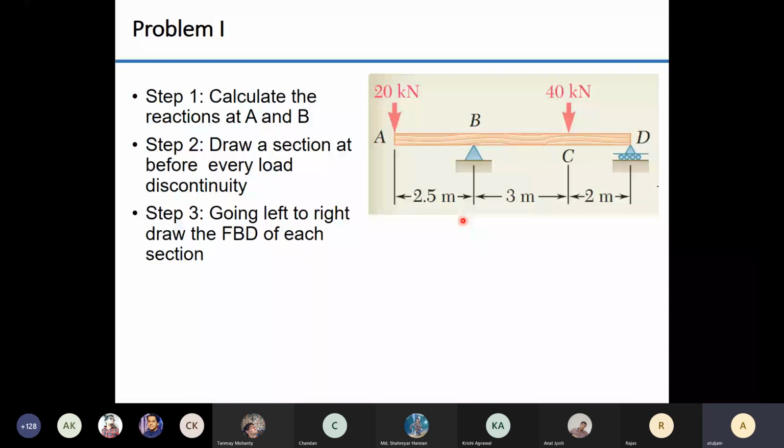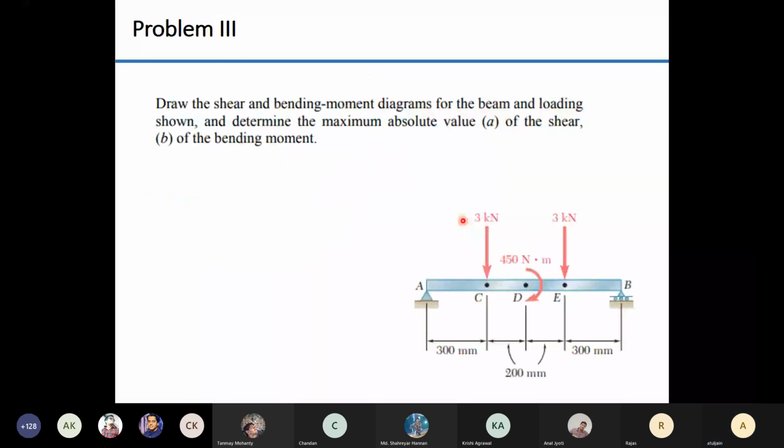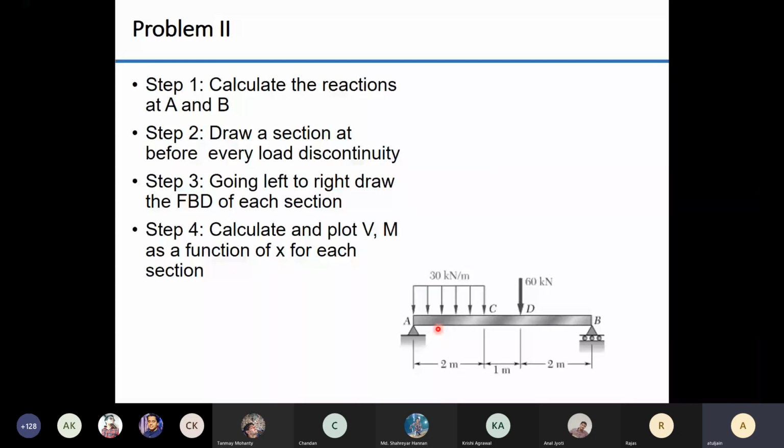Like for example, this is a good example. So let us look at this problem, okay? Now in this problem, I have a beam which is subjected to a point load, which is also subjected to a uniformly distributed load at some point. Now, you know how to draw the bending moment diagram if only the uniformly distributed load was present and if only the point load is present. You could draw both of them separately and add it up. Principle of linear superposition holds. Or if you are comfortable, you can solve both of them together also. But only these three things are there: point load, uniformly distributed load, and moment. Okay?